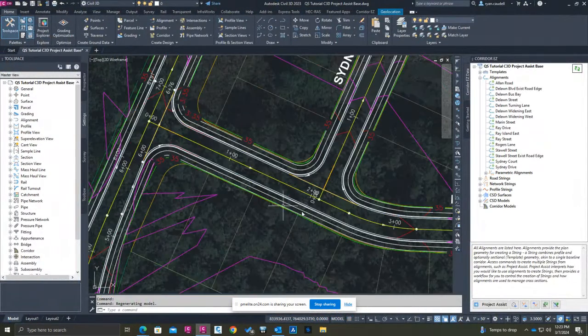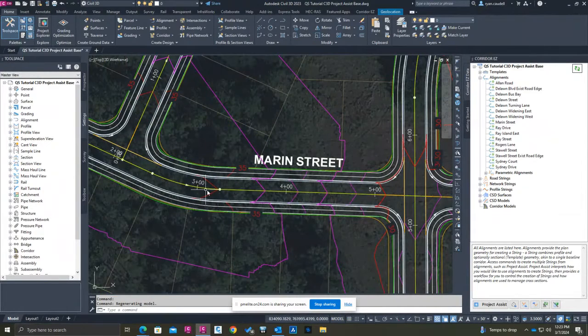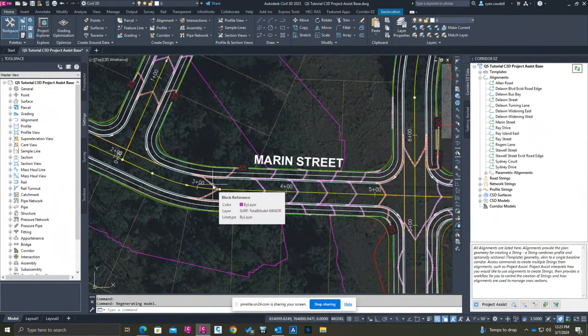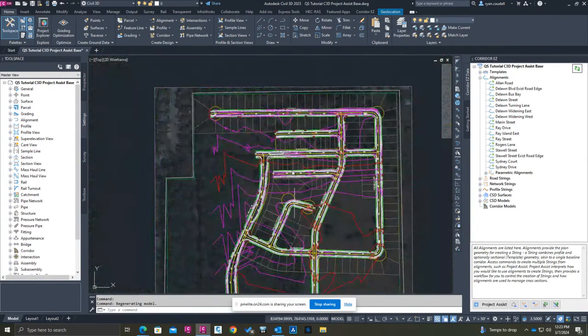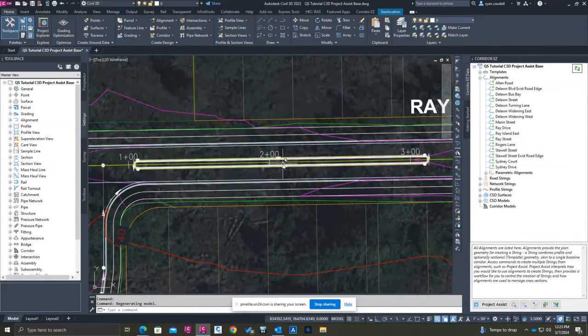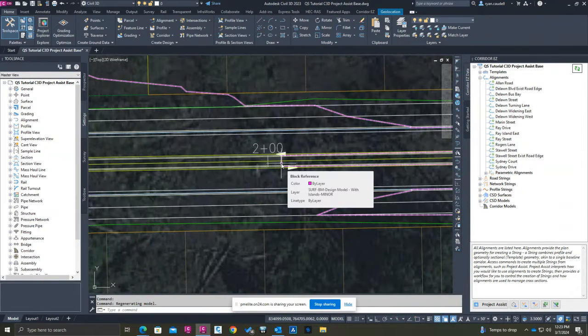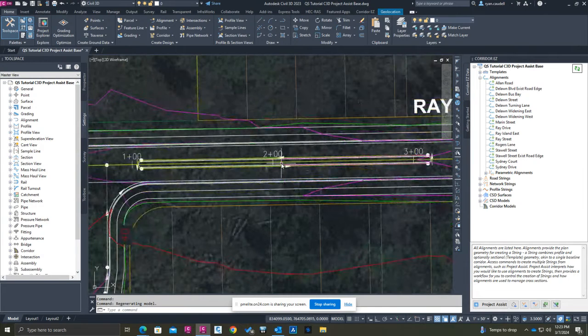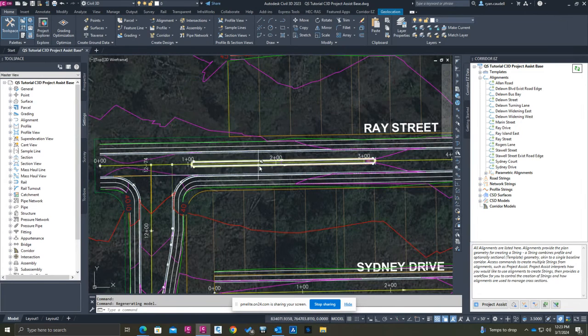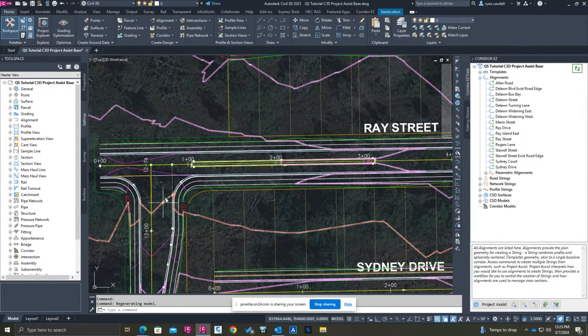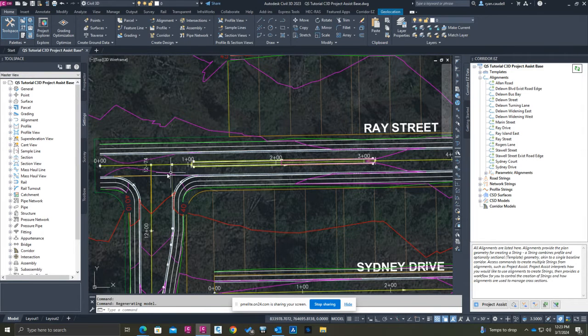And again, as we take a deeper look, you can see that we've got a surface created. Actually, there's a couple of different surfaces. The reason for that is because if we go over to our island here, you'll see that we've got a surface contour that's following the island. There is a surface that was used to drape the island information to it. So that's where you come up with a second surface. And then we've got our original surface, which was the roadway design.